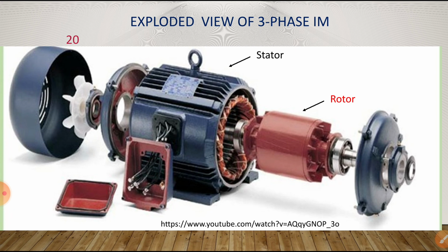The induction motor is classified based on its number of phases and the types of rotors used in it. Based on the phases, whether it is single phase, for small HP purposes, fractional HP to some small amount of HPs, for low power usages. For more power we can use the 3-phase induction motors. And based on the rotor, whether it is the squirrel cage rotor or wound type of rotors. What are these rotors? We will see in the immediate next class.